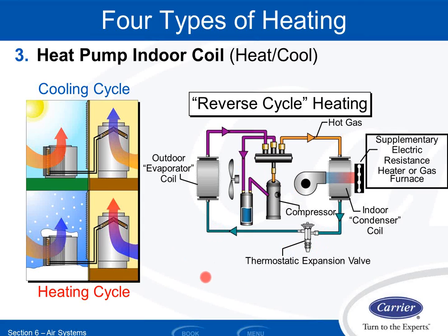Now, the interesting thing about a heat pump is, usually I ask a class how efficient it is just to see the guesses, but since you guys are all online, I won't do it that way. But usually when I ask folks, they'll say, well, it's less efficient than a furnace, that's for sure. Or they'll say, well, it's probably the same as electric heat. It's probably 100% efficient because it can't be anything more than 100. In reality, a heat pump, depending on the outdoor air temperature and the design of the heat pump, is typically between 200 and about 450% efficient. That means for every kilowatt hour of energy that I buy from the electric utility, I'm getting 2, 3, 400 kilowatt hours of energy out of that thing, right?